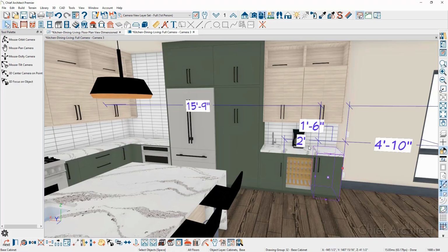Row number 1 is locating cabinets and other objects around it, and row number 2 is locating the walls around it. Let's take a look at how you can edit 3D temporary dimensions to be a little bit more usable for the task at hand by going up to the Edit Active View button.